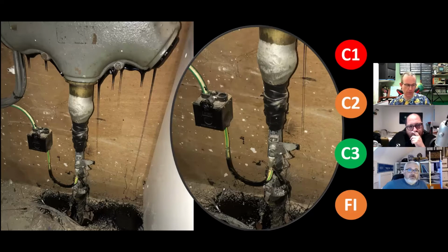Is it fair to say as well, JW, that the intake cutout is the first real place that heat impacts that supply cable? Having worked for EDF, I always used to ask this question on buried cables and heat dissipation. I was always told it's really cold in the ground, so you don't have to derate a cable in the ground that often, because the first time that heat really affects them is when they come out into that supply cutout, where it starts to realize there's a big load on this. And over time, yeah, you're right, it's pitch.